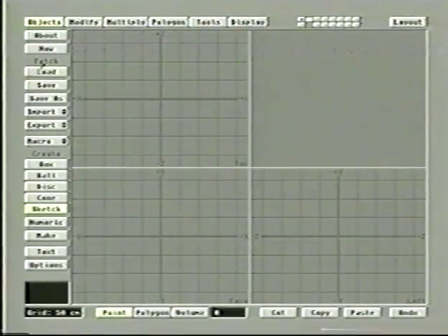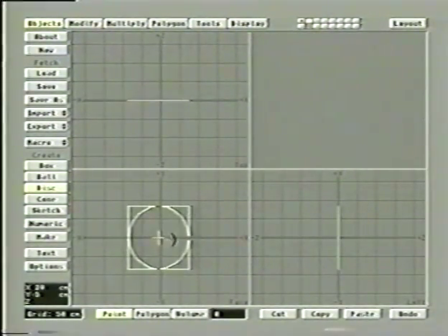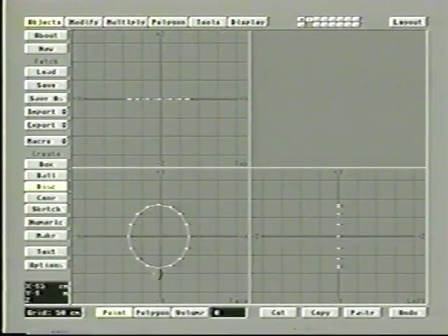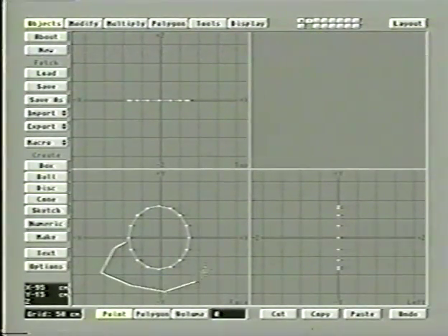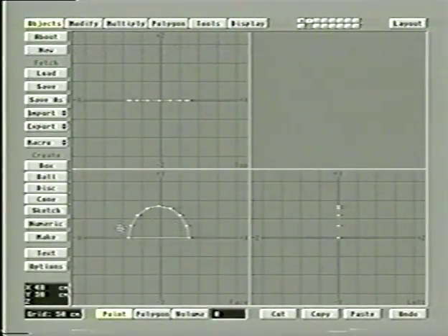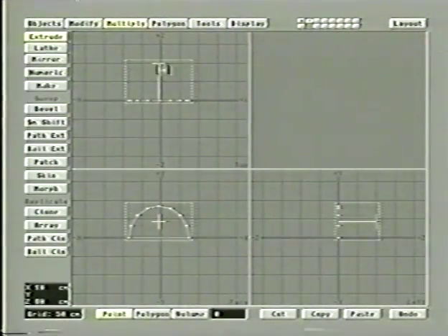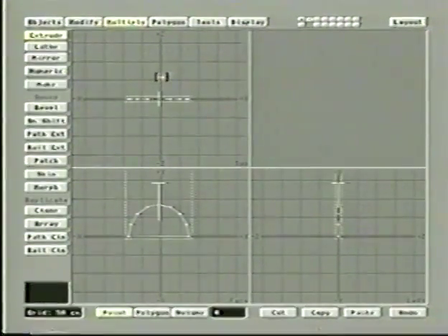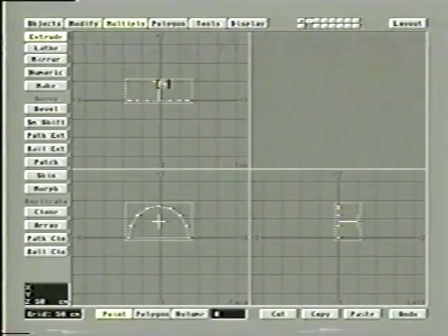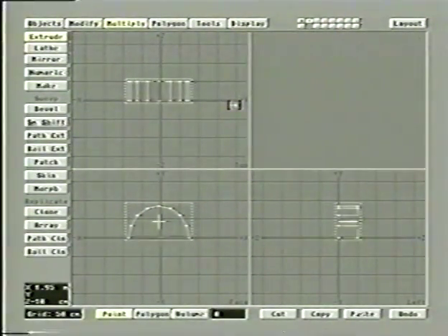And just to do a quick recap, we've already seen it once, but if we take a shape, I'm going to drag out a disk here, and I'm going to make it a sort of semicircle by picking the points on the bottom and cutting them away. So you have a semicircle shape here. What an extrude does, extrude pushes it off into the distance. It takes this 2-dimensional shape and gives it depth, or in other words, 3 dimensions, by pushing it off into the background. That's extrude. Now, there's another type of extrusion you can do called rail extrusion, and it works with a path usually best drawn by using sketch mode.